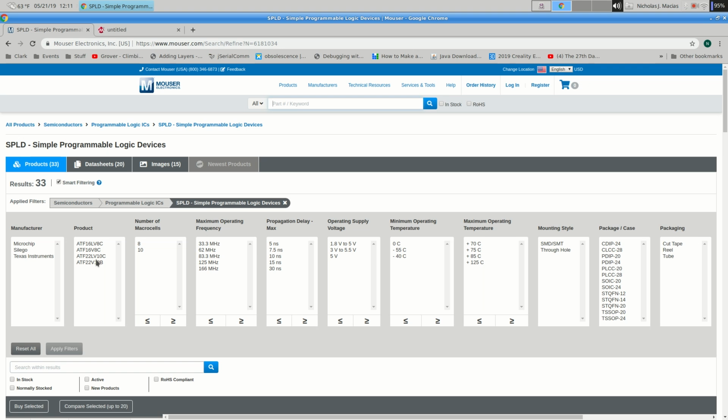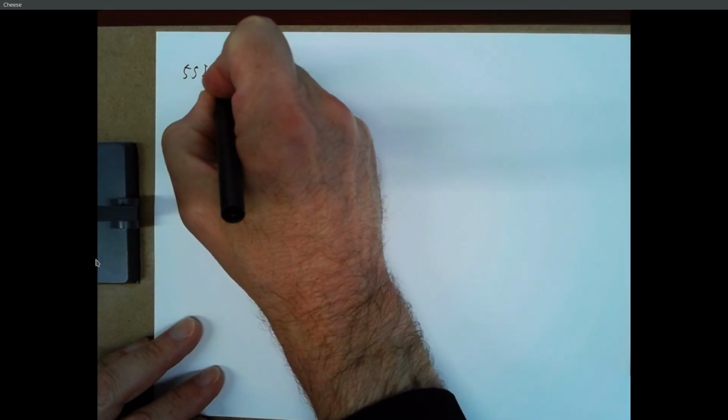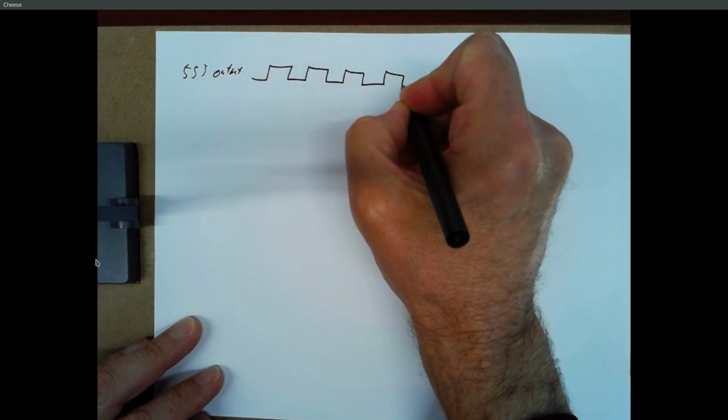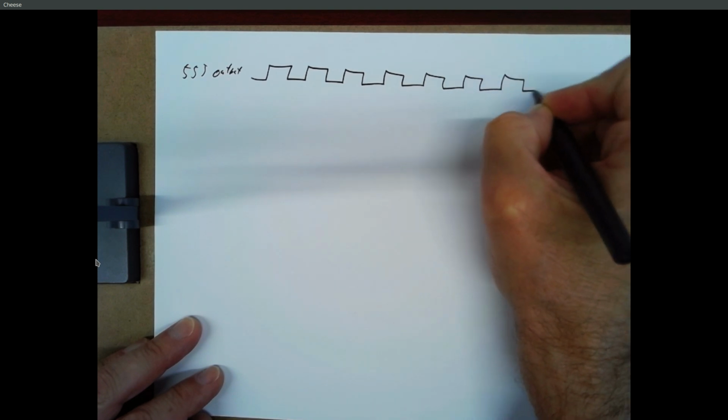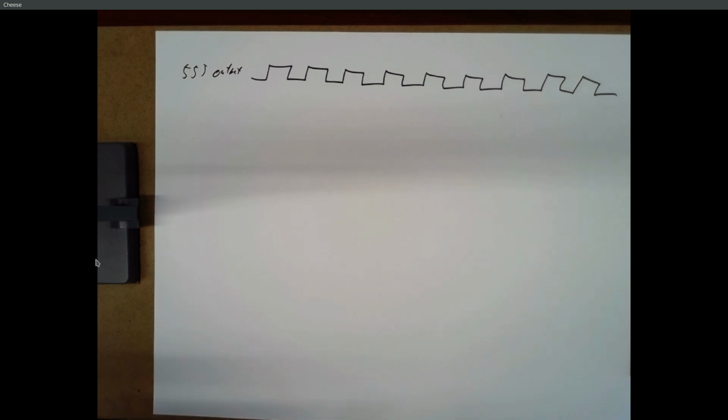Yeah. Actually, on the lab, it asked to do a timing diagram. I wasn't sure what it was asking for. I was assuming it was for the 555 timer, or was it over all the components? So this was the one where we said you can have a 555 output. That's your clock, so that's just going up and down. It's actually not symmetric, but it's faster to draw symmetric. So that's the clock that's feeding into what? It's feeding into a counter, right?